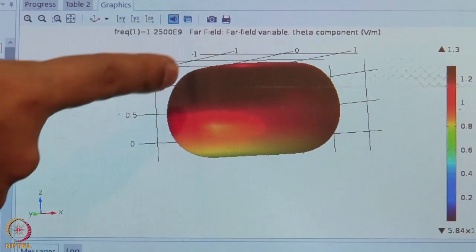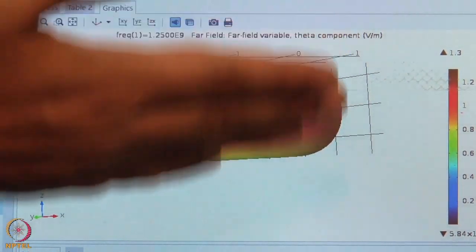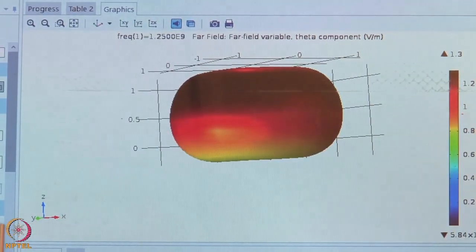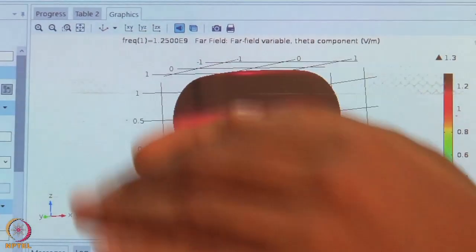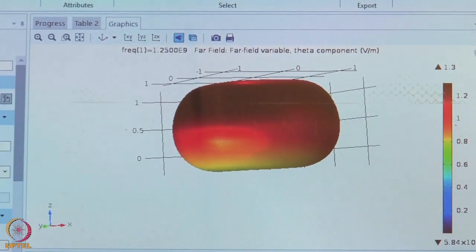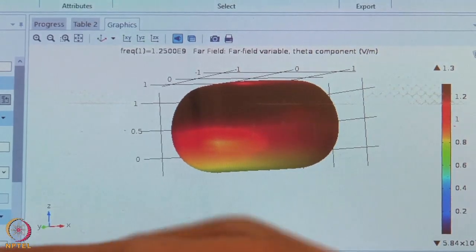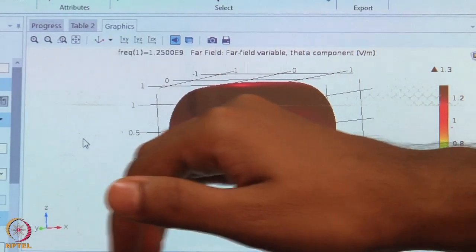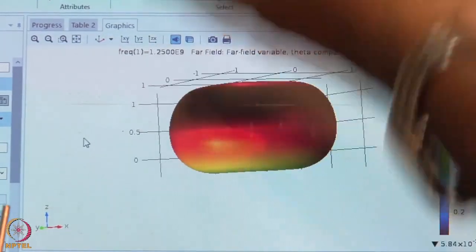So what you're plotting here is the E field, and the reflector plane is pushing everything on the upside. Without the ground plane, what would it be? It will be like an apple. Yeah, so the apple maximum will be here. So the maximum is a bit shifted upwards. Here, where 0 is the ground plane, the maximum is shifted.